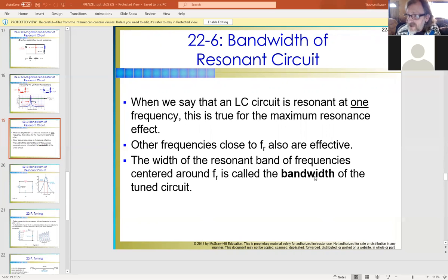I mean, ideally, of course, being the 50 kilohertz, but if we were to run, say, 45 kilohertz, the circuit would still perform well. We wouldn't notice any distortion, any attenuation. And attenuation, that's the effect where you start to get dampening on the signal, so the overall magnitude wouldn't be as high as it could be.